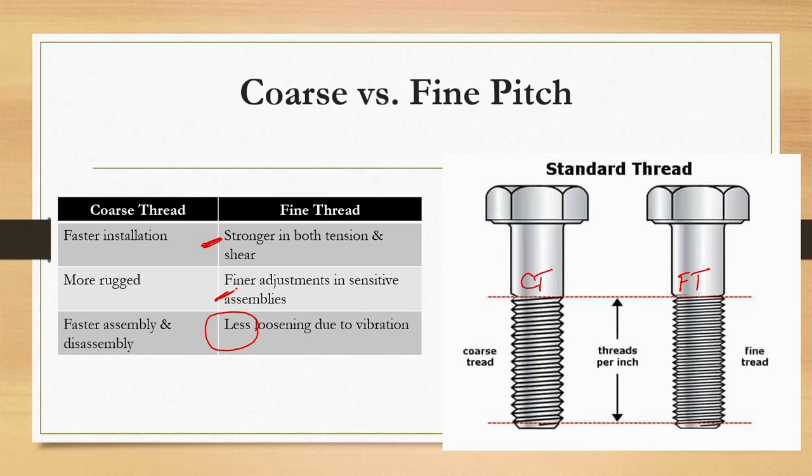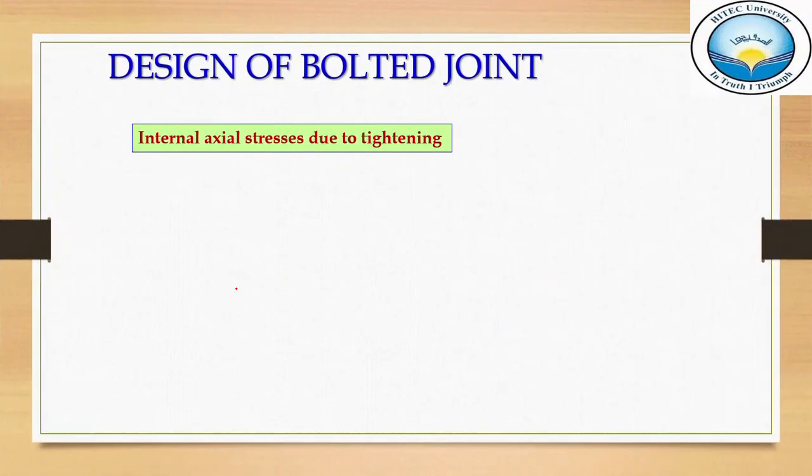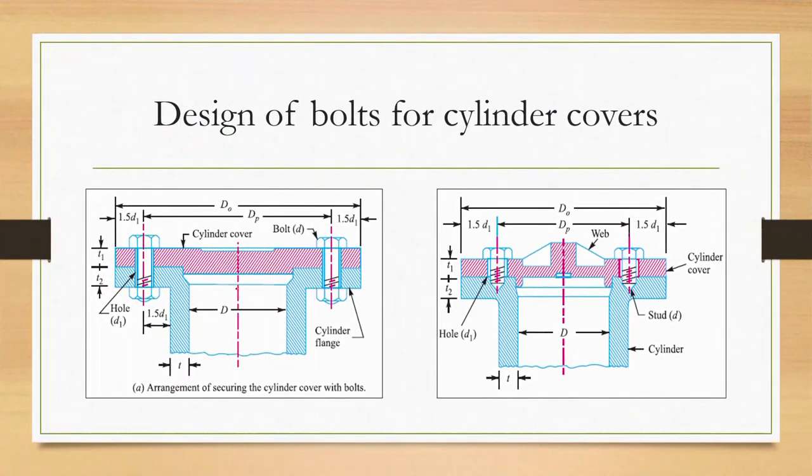If you know that you're using bolts in high humidity applications, like in boilers, or high temperature, then definitely use the coarse threads. Okay, so I will discuss this slide later, but